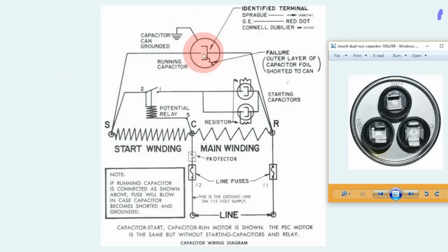What this capacitor does is add in a 90-degree phase shift, which helps correct for the phase shift that occurs in the inductance of the motor. A motor is an inductive load, so there's this thing called inductive reactance. We won't go into that, but it's creating a unity power factor and helping the motor run in the right direction with torque. We'll keep it really simple here.